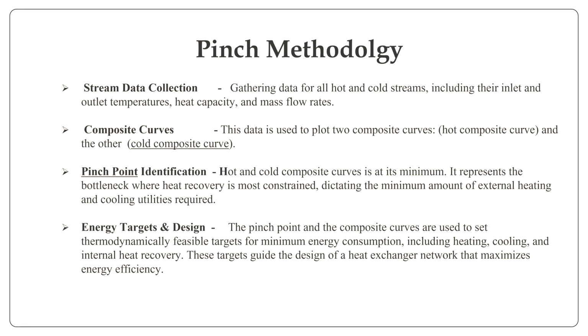Next, the curves should be drawn for the two streams, the hot composite curve and the cold composite curve. After plotting the composite curves, we can identify the pinch point, that is the minimum temperature difference between the two streams. It also dictates the minimum amount of external heating and cooling utilities required.